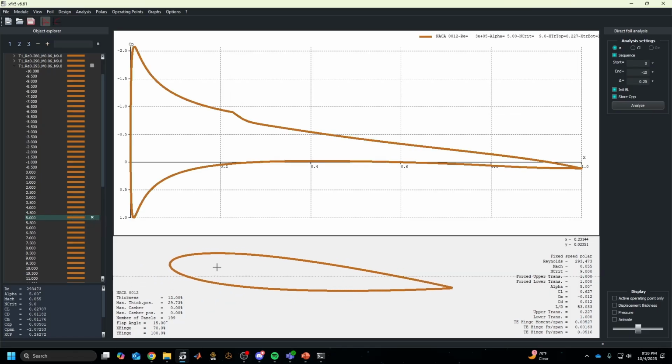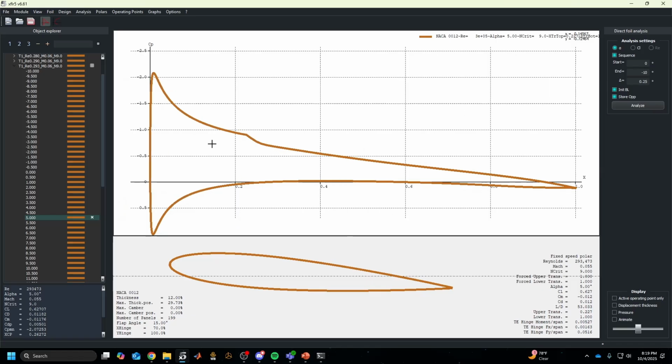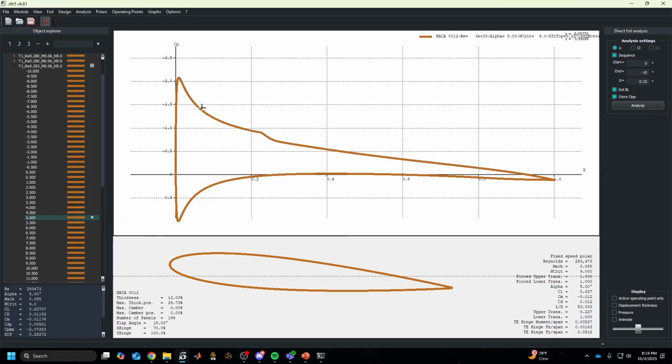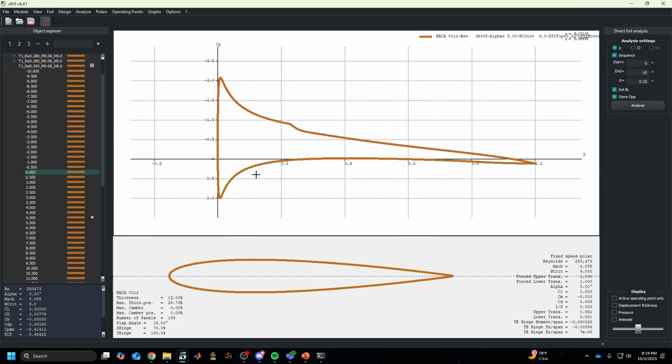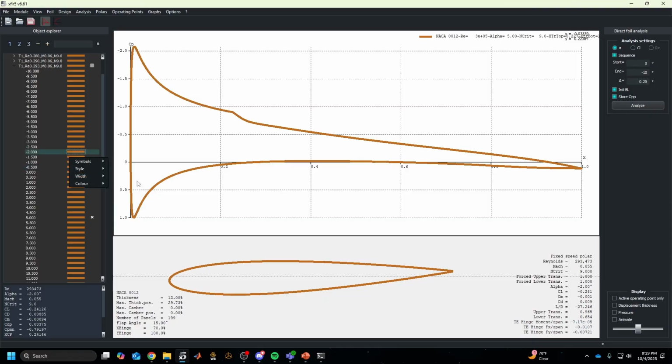Now you can actually see the airfoil here in the alpha it's at. Now, if you remember the CP plot, this is our top surface, because the y-axis is flipped, and you can see our negative CP up there, right? So lower CP on the top surface and higher on the bottom. Now, remember, this is a symmetric airfoil, so we should be getting no lift at 0 degrees alpha. So let's go ahead and see, right? Well, okay, maybe you're getting some lift. But either way, you can see. Oh, I haven't even selected it. That's why.